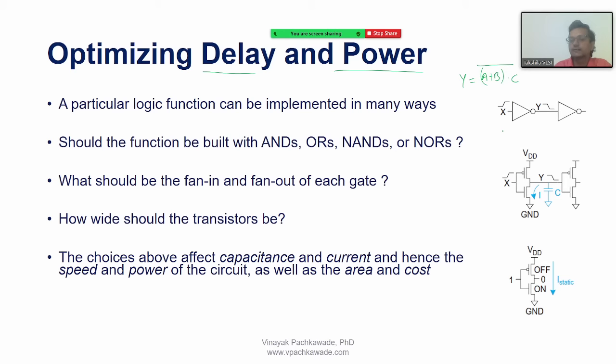We have seen that there are ways to realize it using compound gates or using tri-state. You should know this, right? You should know these answers because these are common questions that might be asked. So we know there are many ways to realize it, and we know that the tri-state approach is compact because it uses fewer internal wires. It also has fewer delay problems because it will be a speedier one, as there are not many stages of logic from input to output.